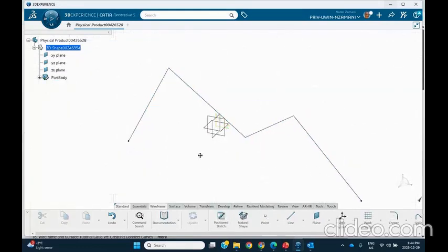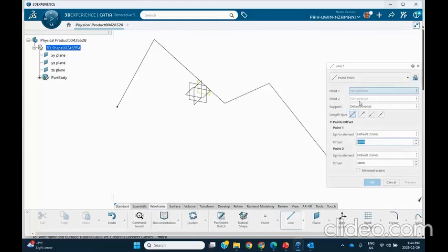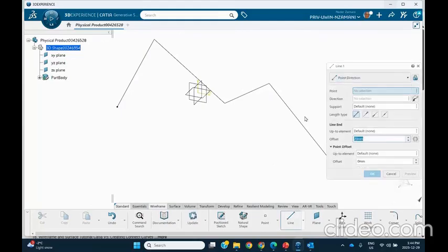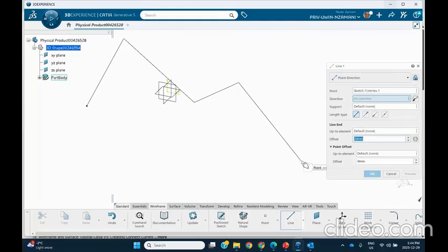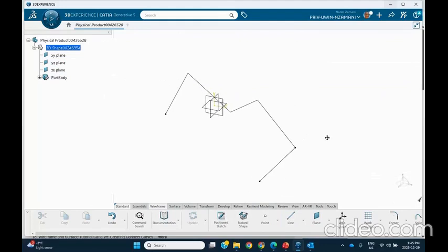And then I'm going to draw 2 lines outside of that sketch. Okay, remember this sketch was in, I believe, the YZ plane. So I'm going to draw 2 lines, point and direction, say this point, and direction being direction X. And I give it a length of 200 so that we can see it better. That's one line.